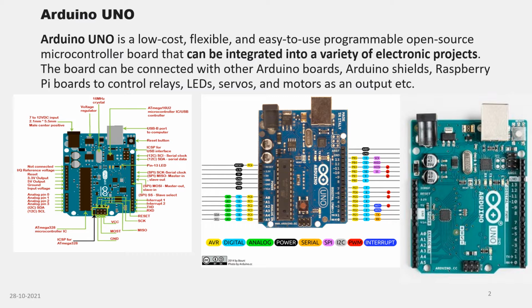So if you need more explanation on this, you can just read up on it. We have some digital pins and some analog pins on the Arduino. Like in the middle picture, from the right hand side, you can see that the digital pins are from 0 to 13. We have about 14 digital pins, and some pins are labeled with a tilde: pins 3, 5, 6, 9, 10, and 11.